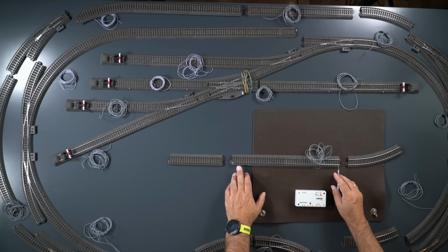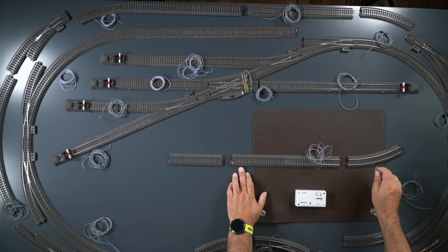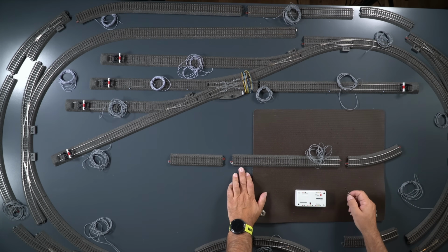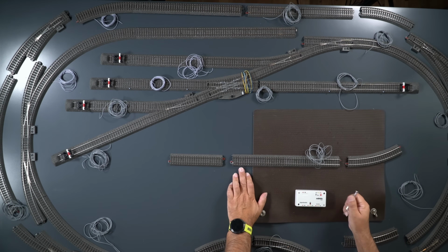And if, for whatever reason, the locomotive goes too far out of the braking section when the signal is red, then it will end up here in the third isolated section, so to speak, and there the locomotive will be emergency braked. For this, I also have a separate track which is then supplied accordingly from this red section.